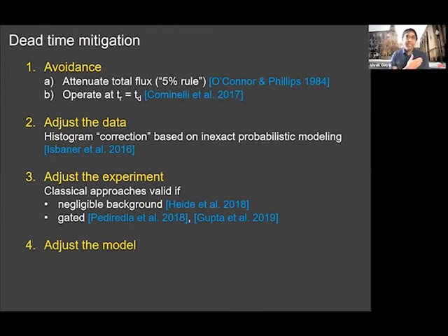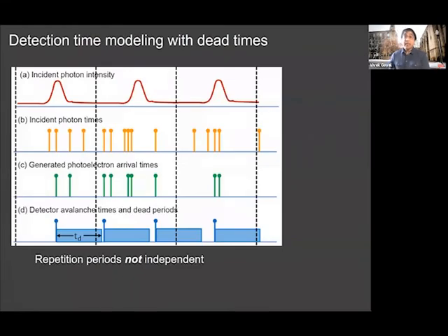It's sacrificing the on or active period of your detector just to make your subsequent data processing easier. Our approach is to adjust the model of the scene response to be able to obtain optimal estimates despite the various restrictions above not holding. The simplest modeling of the effect of dead time is just a bias toward earlier detections. That's that little bit of a forward shift of the peak.